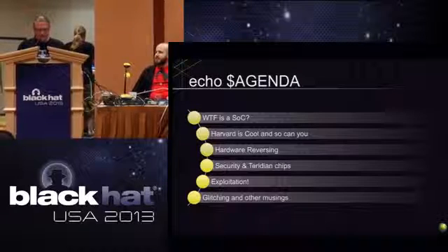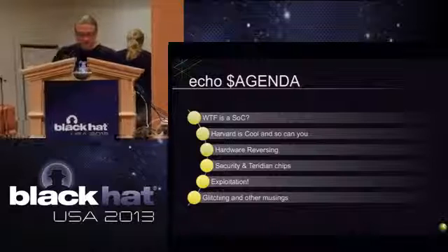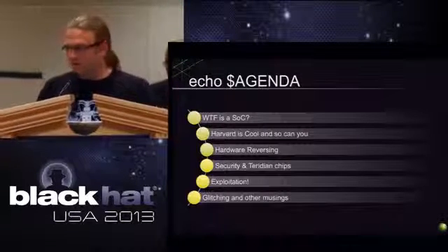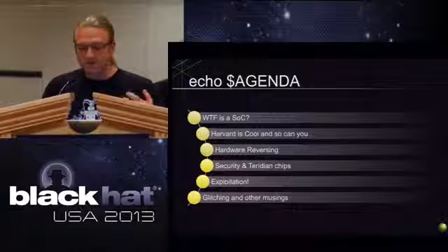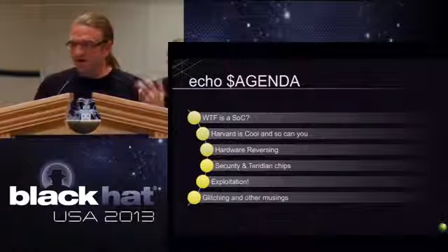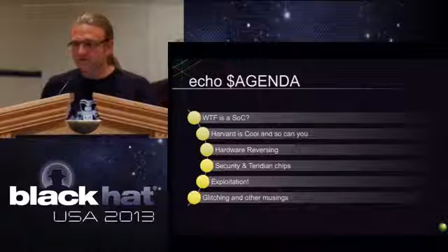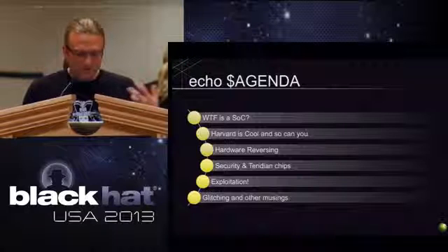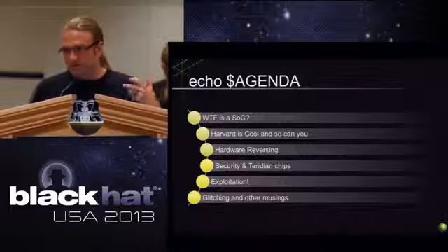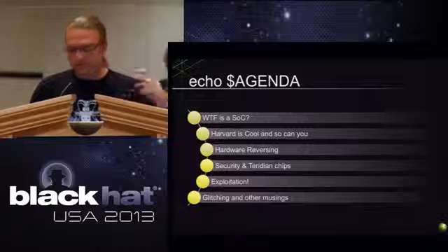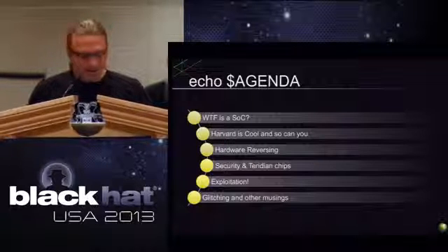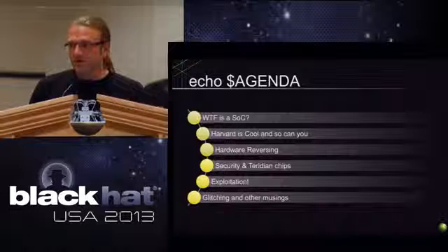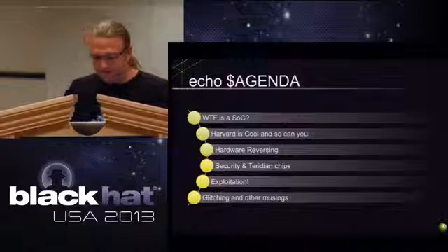So agenda, we're going to go over just what a SOC is in general. Then I'm going to actually dive into why Harvard chips are cool, why we don't actually see very many of them, and just the mental shifts that you have to do between the x86 von Neumann-esque architecture that we're used to and actually exploiting Harvard. We'll go into just the general hardware reversing process that we use, and from there we'll transition into the actual Teridian chips that we're going to talk about. We'll do a full live exploitation, and then we'll also talk about glitching and other more advanced hardware techniques.